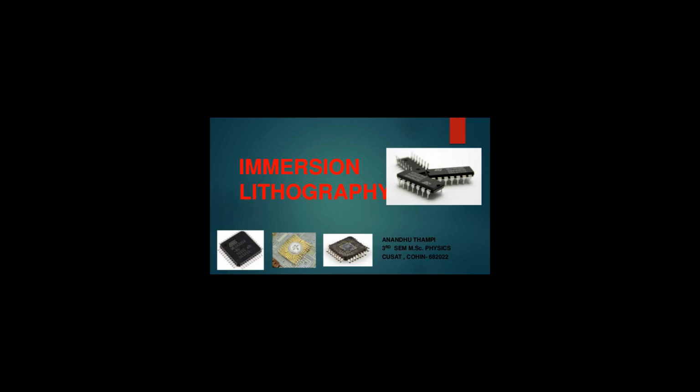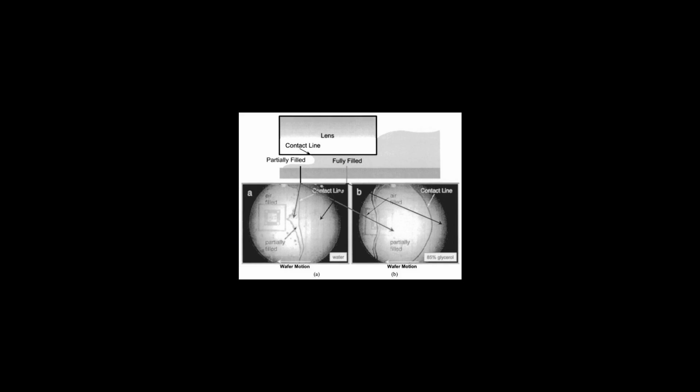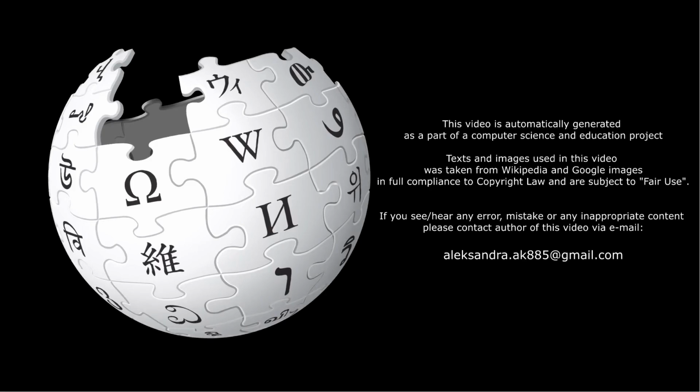However, the depth of focus, or tolerance in wafer topography flatness, is reduced compared to the corresponding dry tool at the same resolution. The successful emergence of immersion lithography comes not just from its ability to extend resolution and depth of focus, but also from its timely introduction to the industry, e.g., IBM, AMD, between 65 nanometers and 45 nanometers nodes.